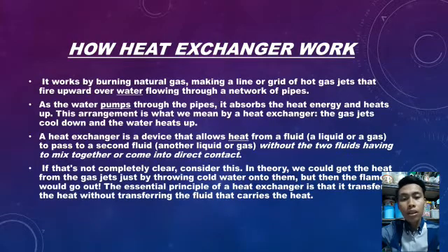And lastly, that's not completely clear. Consider this. In theory, we could get the heat from the gas jets just by throwing cool water onto them, but then the flame would go out. The essential principle of a heat exchanger is that it transfers the heat without transferring the fluid that carries the heat.